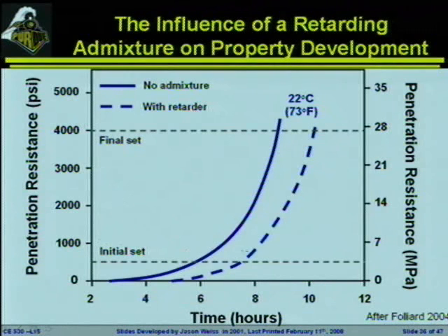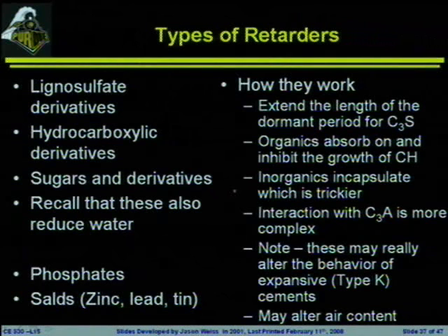Again, the idea of penetration resistance versus time. If you have no retarder in the mixture, you're going to see this type of penetration resistance curve. You add the admixture, you can see that we're going to delay the time of initial set, delay the time of final set, and that's really what we're wanting out of these mixtures.